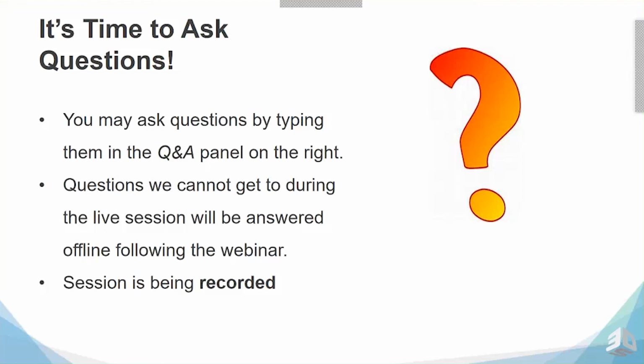It's taken me a little while to do, but I kind of have an 80-20 rule where I'll get a part to where I think it probably has an 80% chance of finishing. I kind of want to leave some chance for some failure and really validate my assumptions that that part or specific feature is going to be a problem. So if you do that intelligently, maybe 2 to 5 for a typical part, you might have a good part at the end.